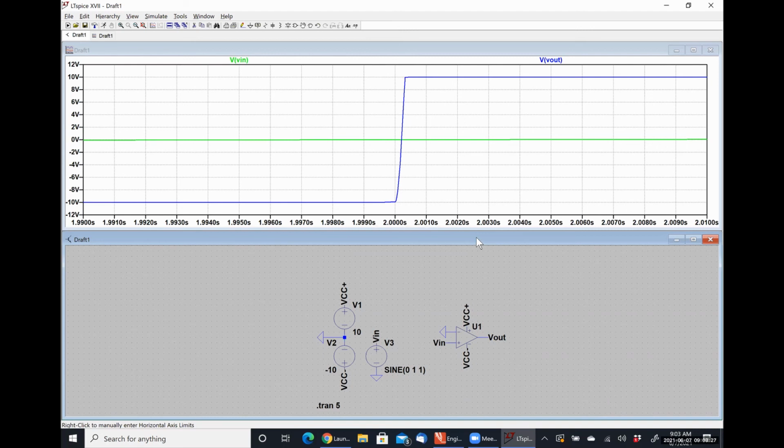So there is an actual amount of time it takes to transition from negative saturation to positive saturation. But when we're looking at things on a macro scale on the order of volts, that linear range of only negative 100 microvolts to positive 100 microvolts is so small on that scale that those lines appear effectively vertical.